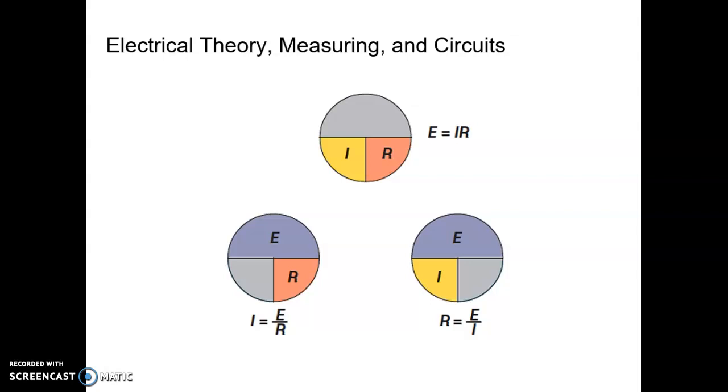So by using Ohm's law and applying what we've learned, we can tell when one thing changes, something else has got to change. Typically, if a customer comes in with a complaint, that's something that's changed. We can use Ohm's law to go back and figure out what's broken and has caused that change that created the customer complaint. Don't worry, you'll have plenty of chance to practice Ohm's law when you get into the electrical classes.